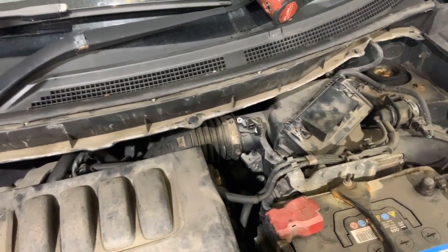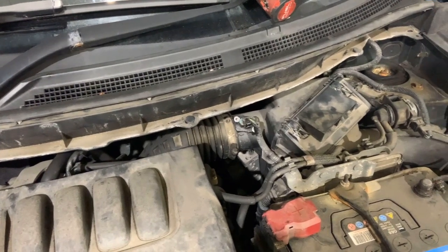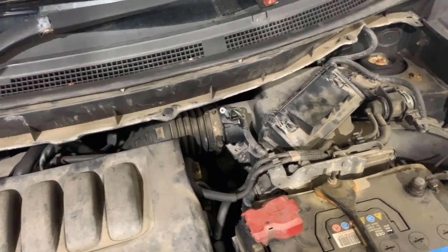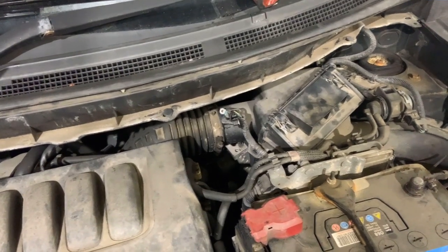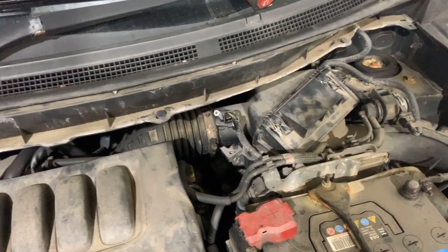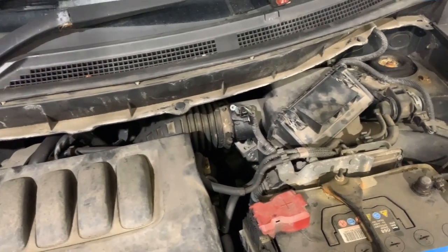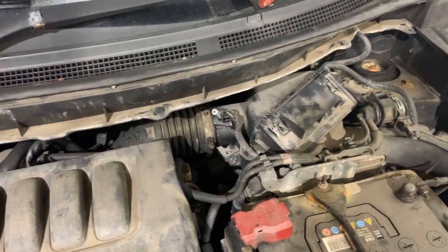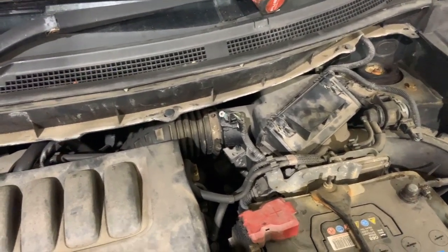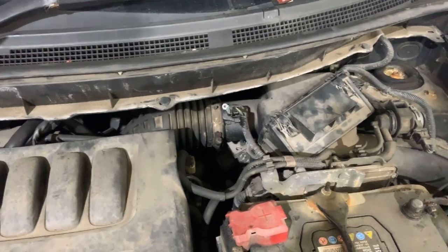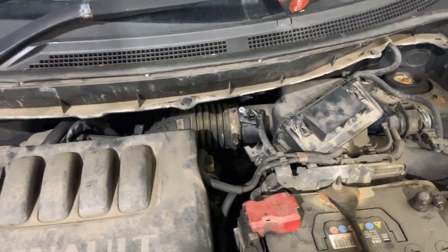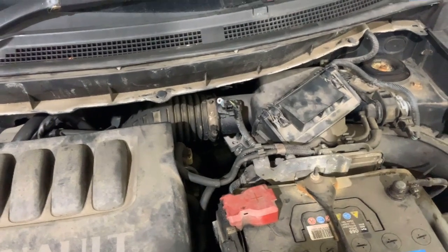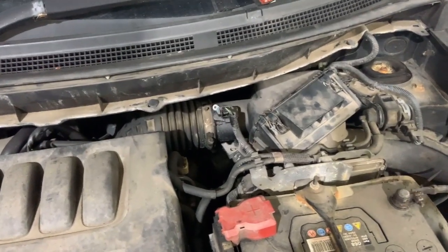They say the substitute value certainly is a good test for most feedback sensors. If you unplug them, most ECUs will actually replace the value with a known good substitute value. There will be exceptions to that, rail pressure sensors and stuff like that. Reason being is for safety. If it doesn't know what the rail pressure is, then it could become dangerous and damage the engine. But airflow meters, MAP sensors, temp sensors to a degree, unplug them, see if you get a substitute value. If you get a substitute value, use it as part of your diagnosis.